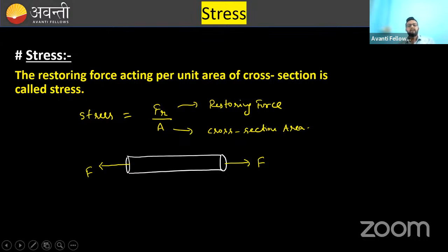This is what stress is. Now, what I have told you in the previous slide is in equilibrium. In equilibrium, the restoring force is equal to the applied force or external force. So what you can write in equilibrium, stress can also be written as F external divided by cross section area.